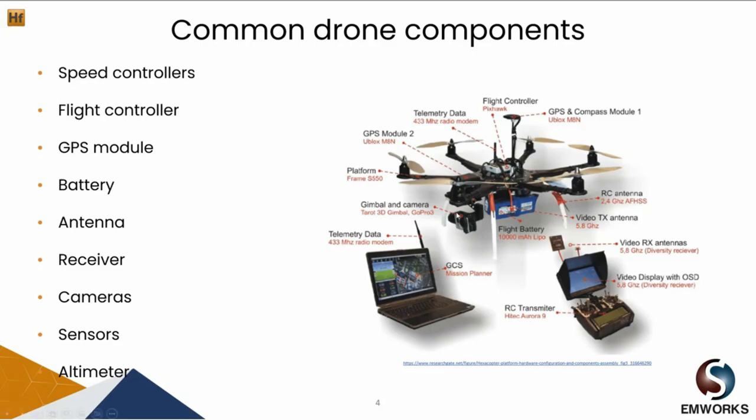As we can see from the image on the right hand side, the controller usually operates at 2.4 GHz range and will carry further than the live video feed signal, which operates on 5.8 GHz range. This means that you will lose your video feed long before the drone will lose connection with the controller. Telemetry module, which is used to get flight details such as speed, elevation, battery level, and all the important data that you can use to keep track of your overall flight performance.